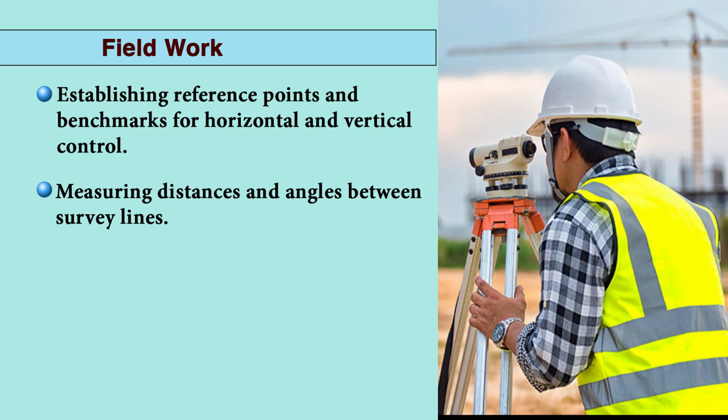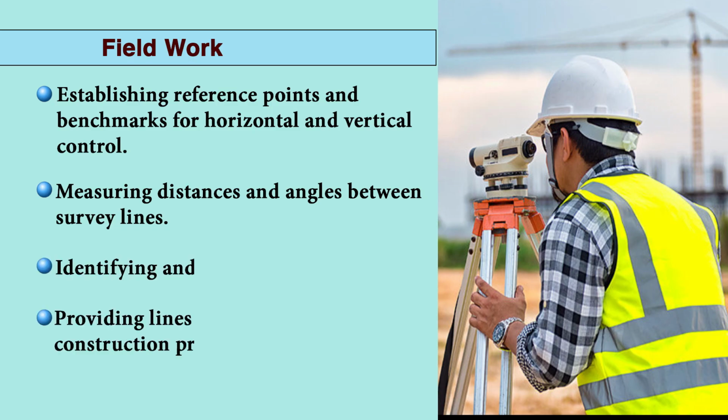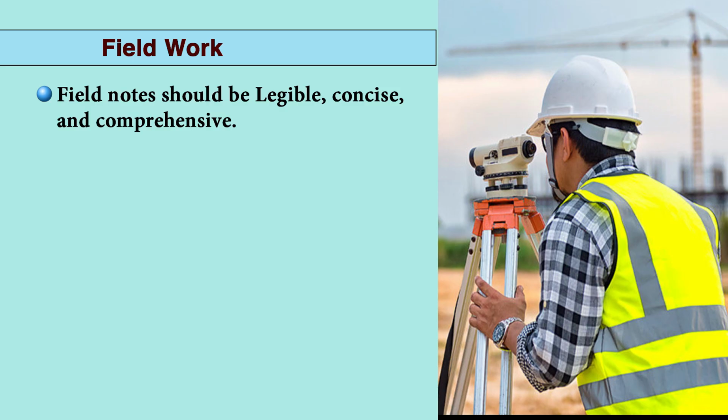The very important one is measuring distance, angles and the elevation in the field. Third one is identifying and locating details such as boundaries, road, buildings and natural features. During a field work, a surveyor must prepare field notes in a proper manner to accurately interpret various survey conclusions. Field notes are crucial records made during field work. Field notes should be legible, concise and comprehensive.